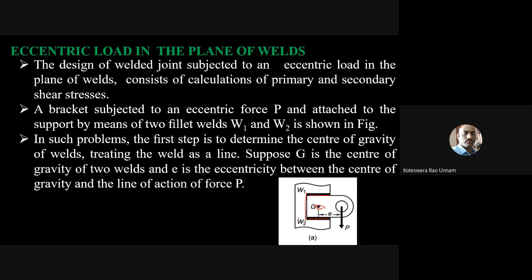So for that, only thing you need to do is identify what is the given weld, so the corresponding weld in the data book. From that, straight away you can pick the formula. Once you pick the formula, take the data from the given problem, substitute that data into the formula, and you will get your X bar as well as Y bar. So like that, first we'll find out the center of gravity of the weld system.